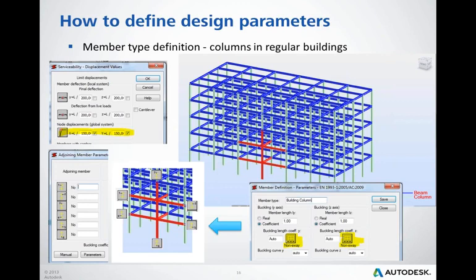So when you have a beam defined as a single element, or another identical beam divided into three smaller elements, you create a superbar to be able to assign the design parameters correctly. For example, if your buckling length is equal to the length of the element, it's rather hard to do so for 1/3 of the bar, right?